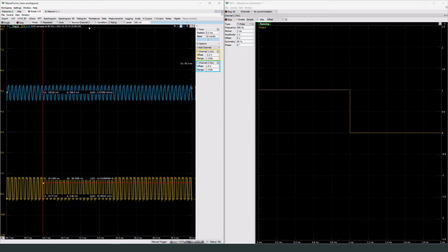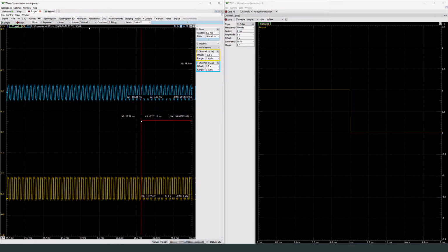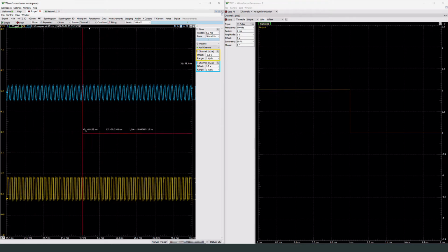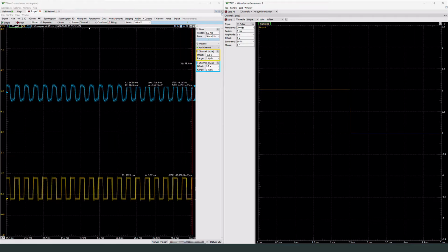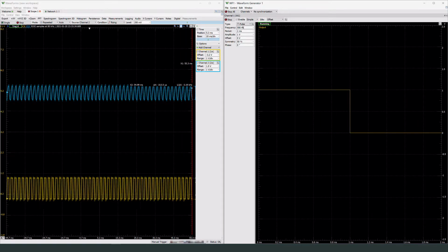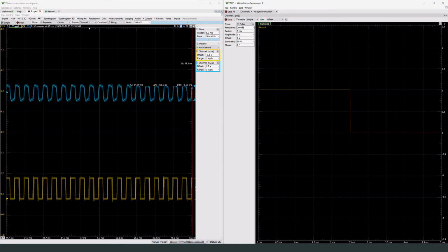What's interesting to note too is that just having a resolution of one pulse per cycle actually gives a pretty decent sine wave with less noise on it. You could only make a sine wave that way, but it works pretty well. So anyways, we'll just show you what happens with the circuit, because we designed it to operate between 250 and 500 hertz. So there's 200 hertz, and here's 500 hertz, and you can see they're roughly the same peak to peak value. So we get what we're looking for here.